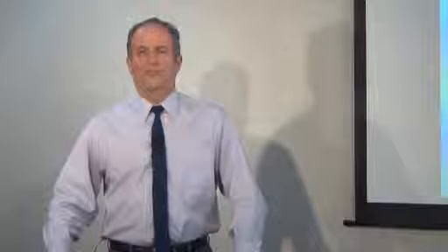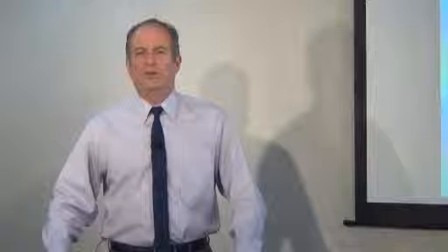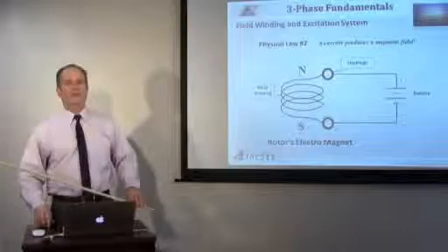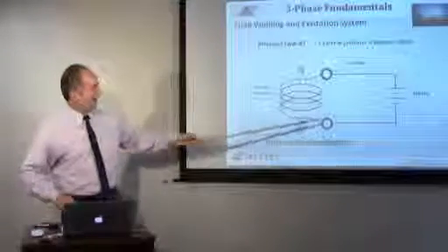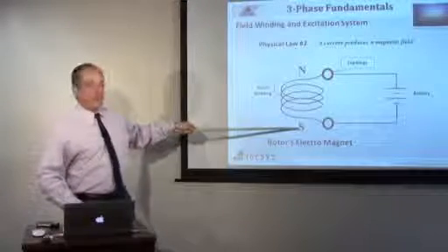Okay, now let's look at the second physics law, where we are talking about the current through a wire will produce a magnetic field. So here we have a coil and we put a current through it. Now this is DC current. We have a battery there and we're putting DC current right through the coil of wire and we're producing a north and a south pole.